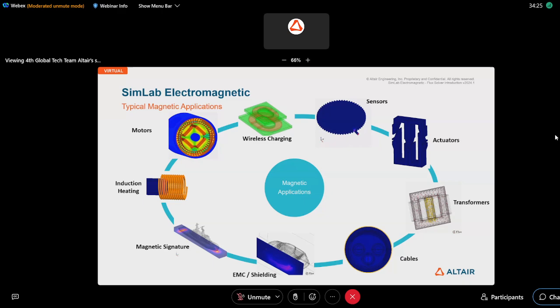We will solve the 2D model, and we use the coupled solution. This is not up to date probably, but to pass the loads to the thermal solver. But we also have the possibility to pass the load mapping in order to perform NVH analysis and acoustic at the end. So we have different solvers in this training, and you will see electromagnetic, CFD, NVH, and acoustic solutions in just one training. This is pretty interesting in my opinion, and you can see the full workflow dedicated to a motor.